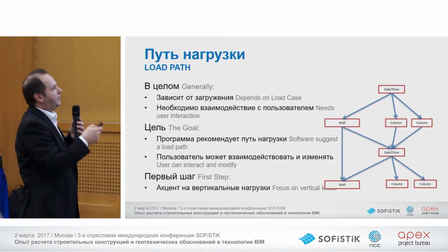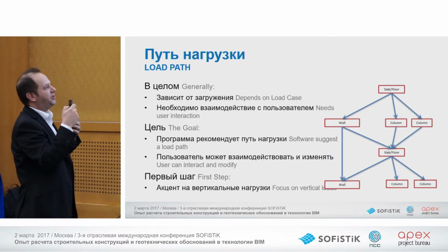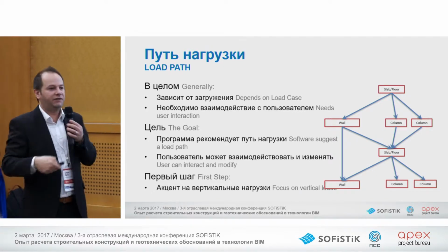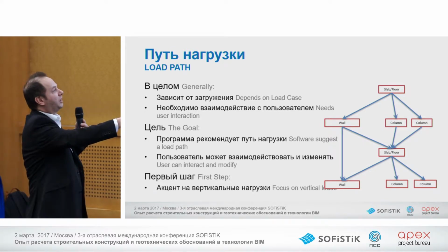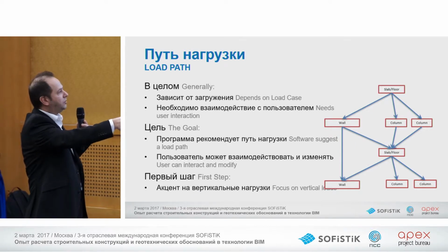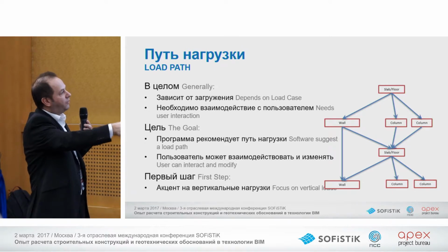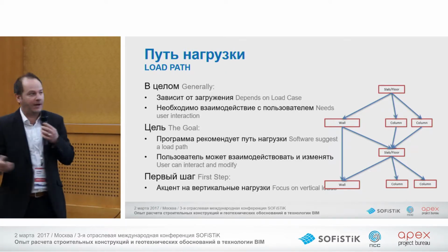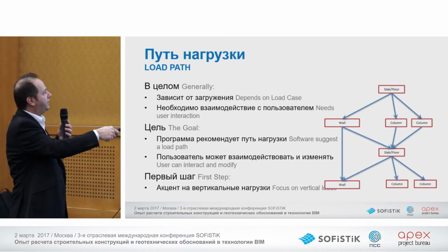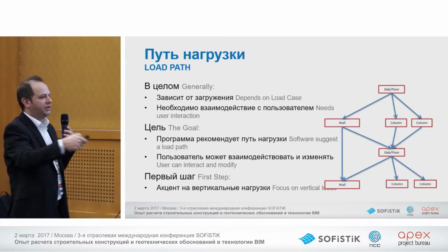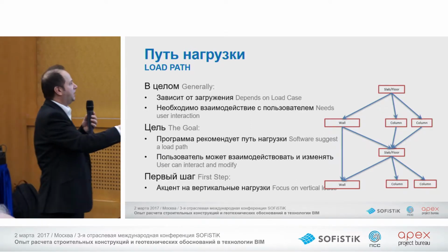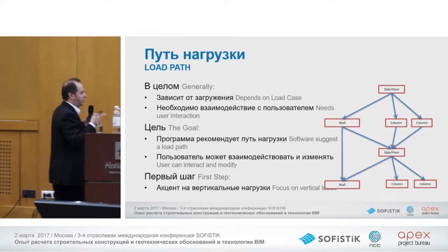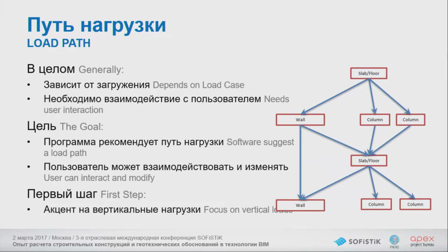So the main point here is that we can have tools that give you a suggestion of your load path, okay? And this could be a theoretical load path, even if this load path is not 100% correct, or maybe also not 100% of the load goes directly into the wall, maybe also some percent of the load goes into the slab, to go from the slab directly into the column. So I think you as a structural engineer have to make that decision, okay? So it means we can give you a suggestion of this load path and try to give users access to this load path. So give the user the possibility to interact and modify the load path. So as mentioned before, we will focus on a vertical load case because all the other ones are quite tricky.